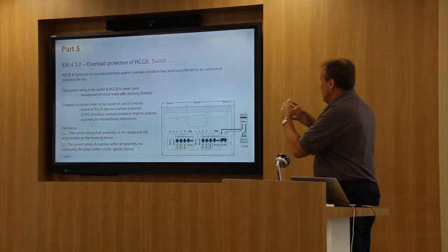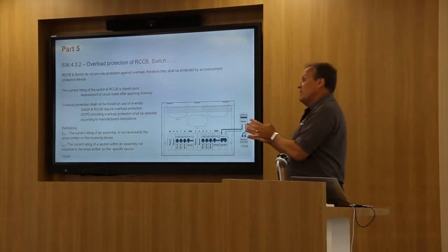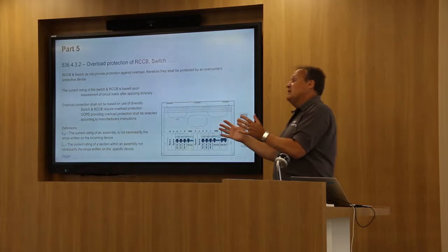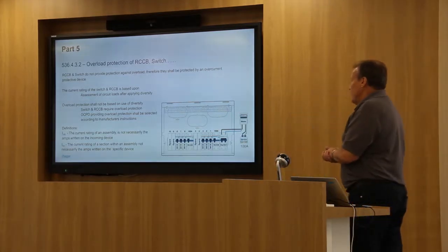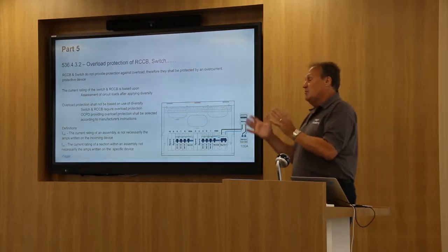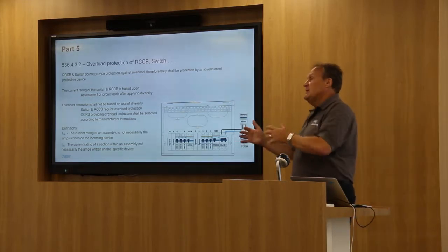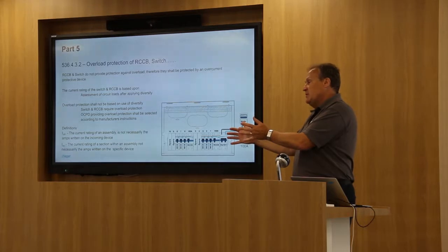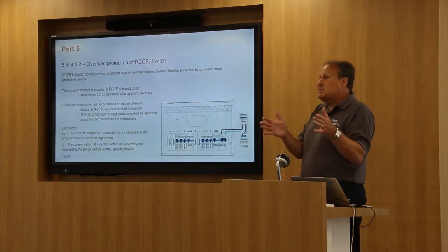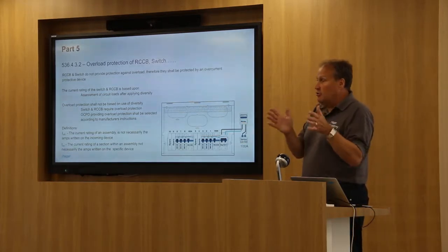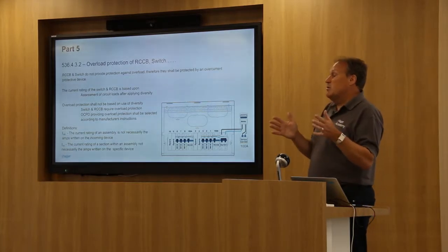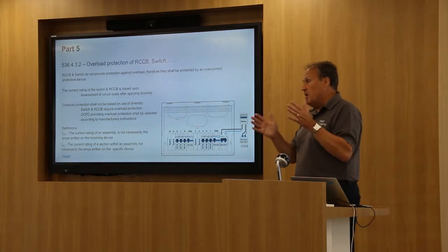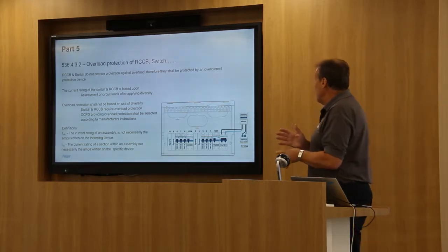So now we have a maximum 100 amp supply, a 100 amp rated assembly, and 100 amp rated subsections within the assembly. It all fits, it all provides nice overload protection, and it makes the job very easy. So just choosing a 100 amp assembly with these devices in, or a 63 amp assembly maybe, if you are sure and guaranteed that the supply to the installation cannot be more than 63 amps, maybe flats and apartments, where it's under your control, is okay then.